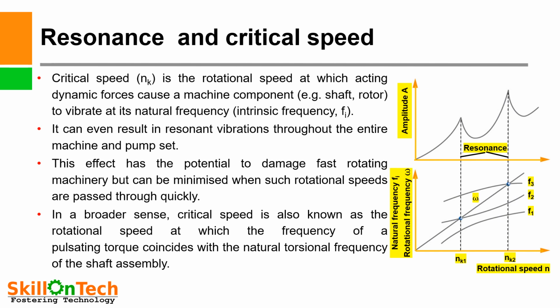So if the natural frequency of the pump shaft or rotor is similar to the frequency of rotation of the shaft, then there may be a resonance and that will increase the amplitude of vibration.